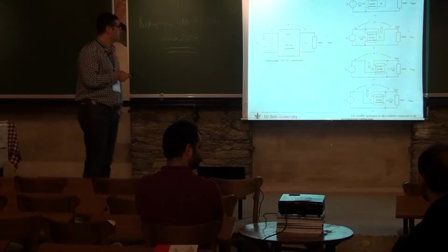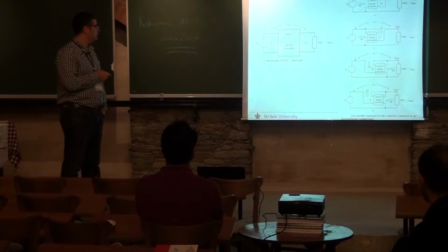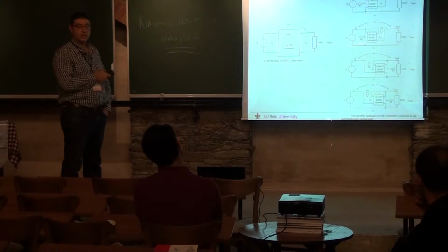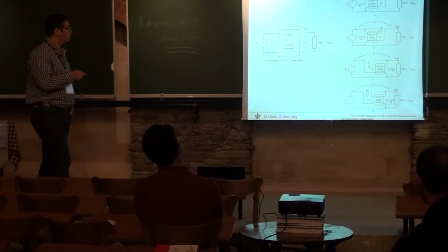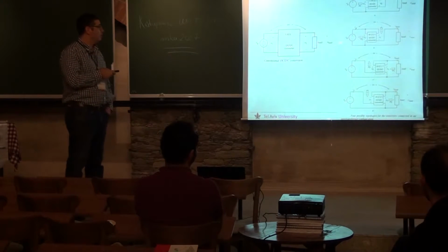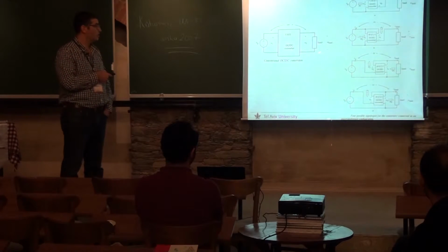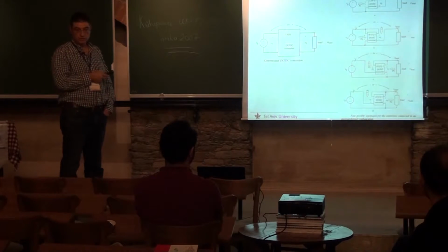Just a simple example. So we already know that if possible, instead of having a converter which processes the entire power through it between the source and the load, maybe we can apply one of these arrangements here where partial power is being processed. Of course, this will be more advantageous as these voltages are closer to one another.